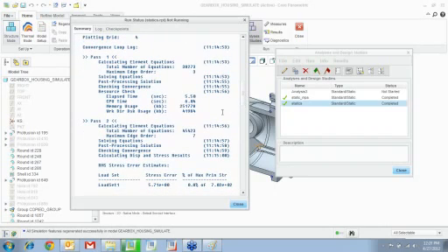ProEngineer runs actually two passes. I'm sorry, I called it ProEngineer, it's Creo. So in the first pass, the maximum edge order of the elements is 3. Okay, so we are using cubic curves to map the geometric boundary. Now it gets a value of all the stresses along each element edge, and then it runs another pass at element edge order 7.